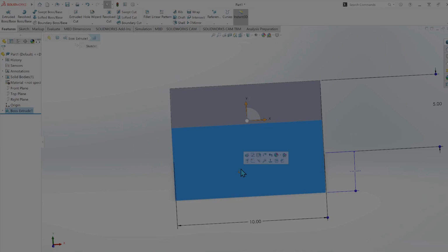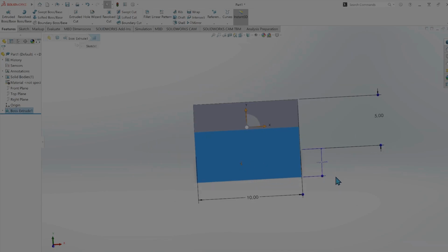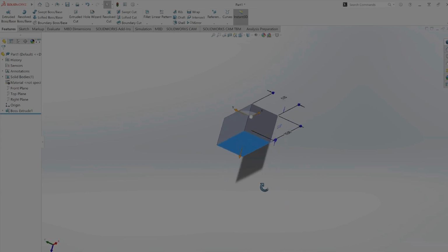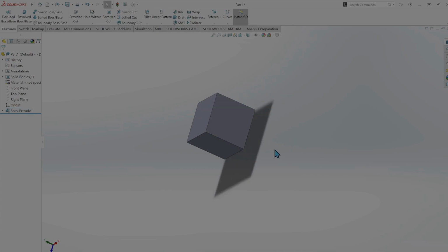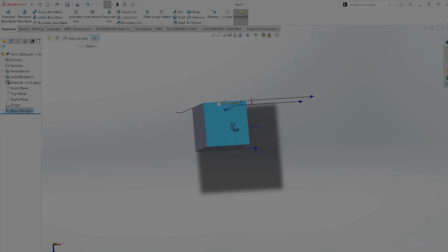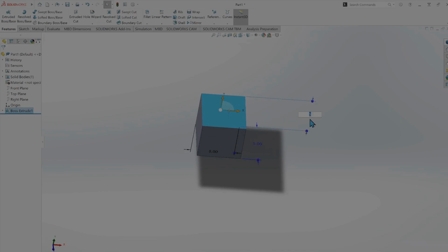And if you want to continue modeling on top of this, first let's start with editing the extrusion. Okay, so as simple as you click the model, the dimensions will pop up, and then you click on the dimension and edit the dimension.